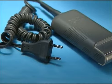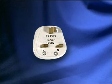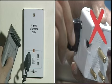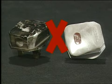This type of 2-pin plug is solely for the use of shavers. A plug should have markings showing the wiring connection, current rating, voltage rating, and the standard with which the plug complies. Don't use any 2-pin plug other than for a shaver. And don't use broken or burnt plugs.